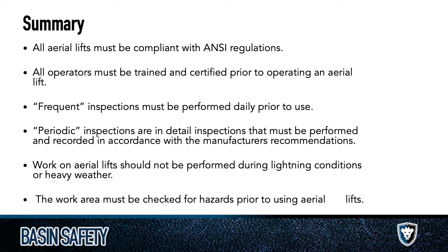All operators must be trained and certified prior to operating an aerial lift. Frequent inspections must be performed daily prior to use, and then periodic inspections are typically going to be your annual ones, and those do need to be documented and maintained for 5 years. Work on aerial lifts should not be performed during lightning conditions, heavy weather, or around power lines, period. So we want to make sure that we're checking the work area prior to going to work on our aerial lifts. And that wraps up aerial lift safety training.